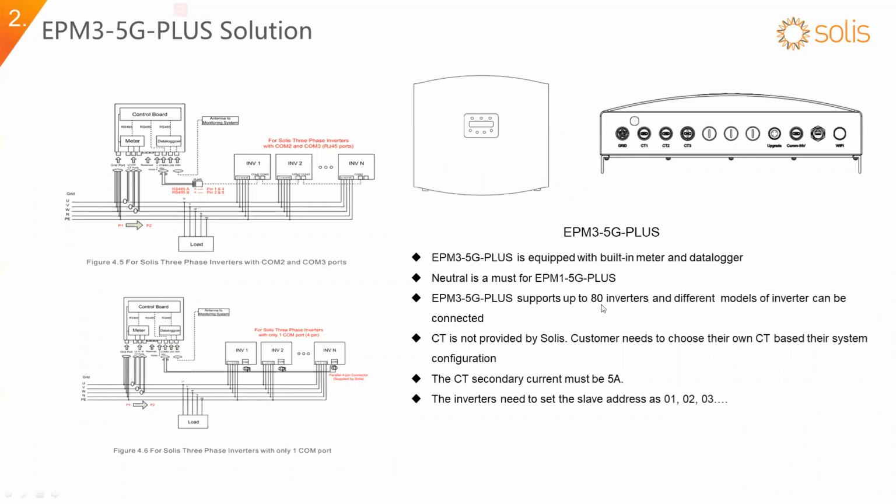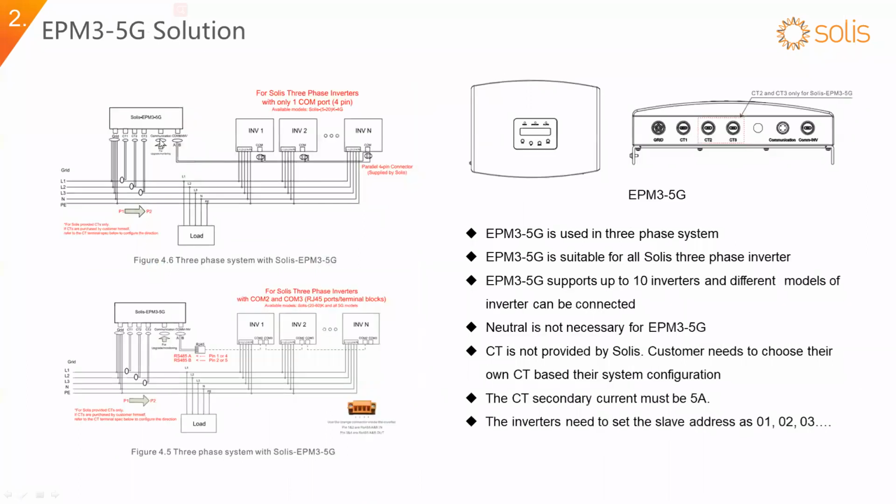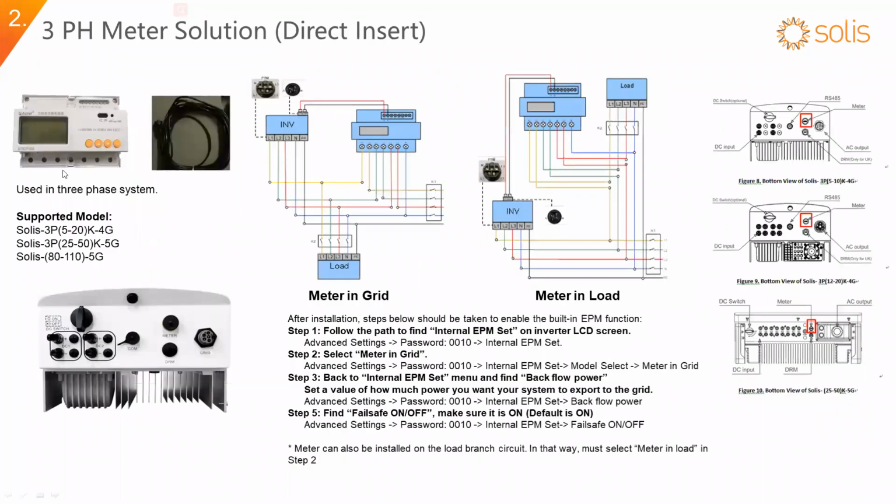Sorry, I mean the zero export meter in the Solis inverter. That is what we call the built-in solution, so you can connect the meter externally. The control function is built inside the inverter, but you still need an external meter to measure the grid connection point.